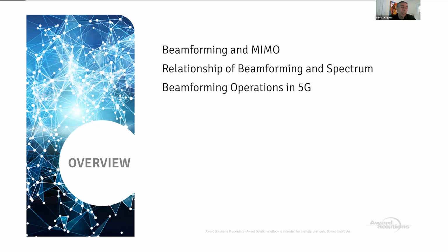And you can start thinking of a beam as a spotlight in a concert venue, right? Rather than having one light covering the entire stage with a given beam or giant light, we use several spotlights in order to increase my signal when we deliver data to my subscribers, okay? We're also going to talk about the possibility of using beamforming in low range, in frequency range 1. Frequency range 1 is frequencies of operation below 7 gigahertz.